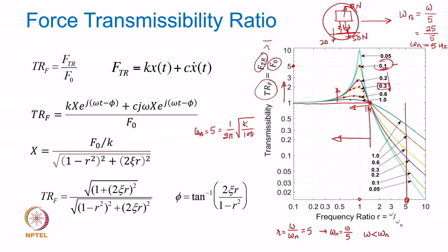If suppose the mass of the condenser unit is 100 kg, you can then work that out, that the value of effective k that you need is going to be 10 pi square multiplied by 100, not divided. So much of Newton per meter, right, that is effective k.